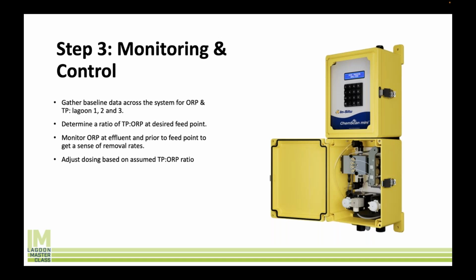And by being able to dial in your chemical dosing, not only are you going to ensure that you're going to hit your limit, but you're also going to make sure you're not wasting chemical, right? And the third thing is you're not going to settle too many solids that you'll eventually have to remove later. So I highly recommend that you do this monitoring and control piece of the overall project, because that's going to help you to be more efficient, more cost efficient, and deliver a better result.